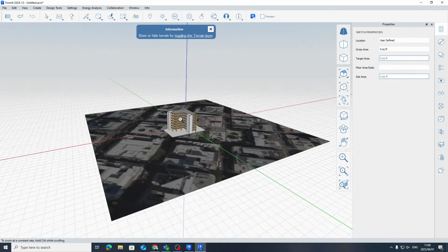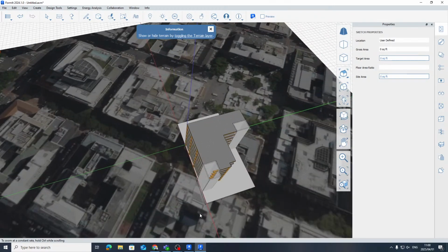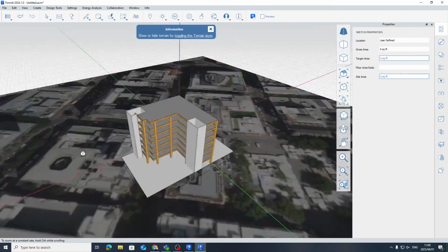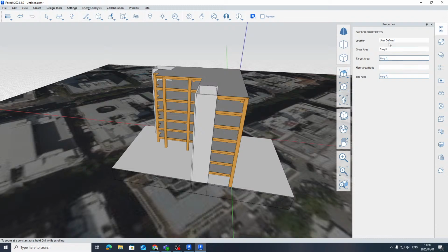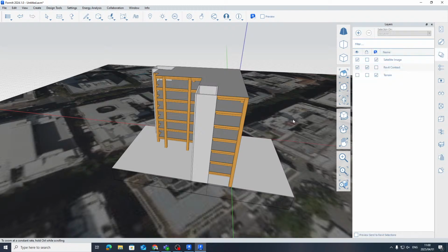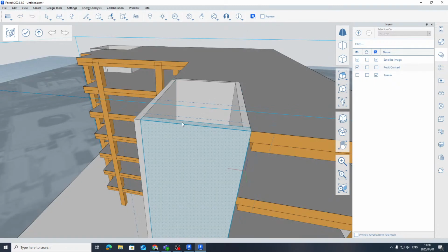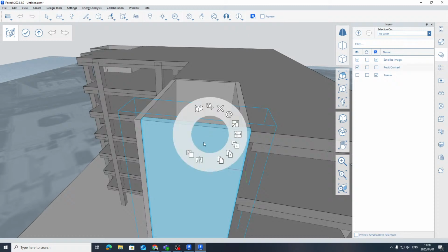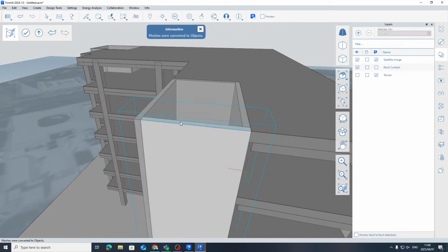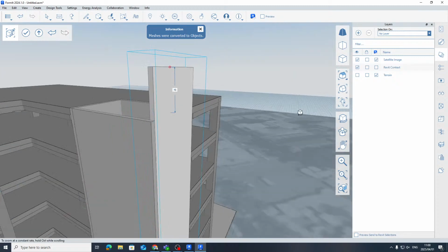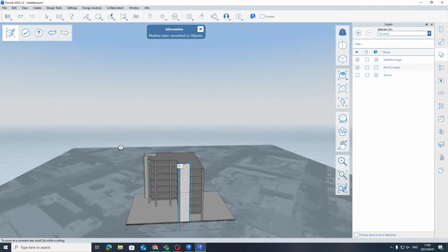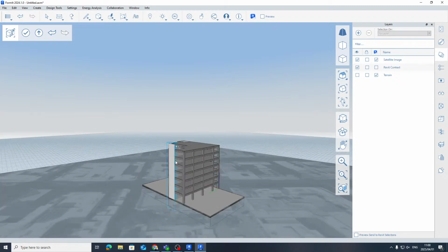Now, what's very cool was, in the past, you could see it exports that whole Revit model into Formit. Then it allowed me on the fly to go and pull the stuff, and it made it into groups that are very usable. Yes, sometimes you could convert these into solids, but it allowed me very quickly to go and remodel stuff in here, and then I could pull this back into Revit.